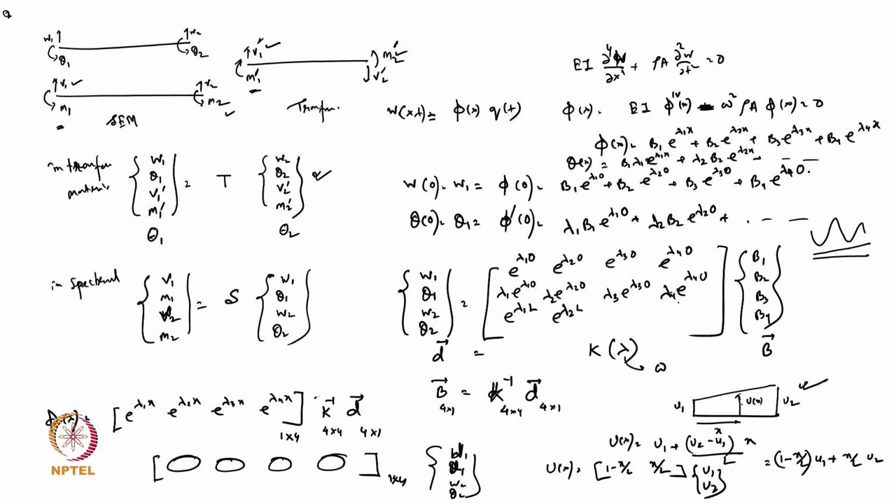Now here, if you know the differential equation or the solution of the differential equation exactly, you can solve the spectral element. But if you cannot form that governing partial differential equation, you cannot formulate the spectral element method at all. It's not possible, because you don't know where to formulate it from. For example, if I give you a problem of a beam having some cutout in between, it is extremely difficult to formulate in the spectral.